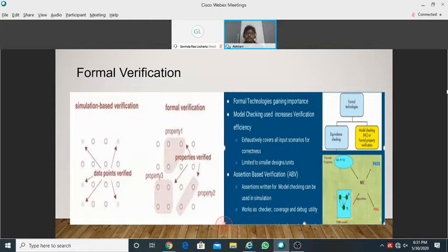Okay, so that is why we need to know what we need to use formal verification for. If you see, formal technologies have two points here. One is equivalence checking. It can be used for equivalence, like given any two inputs, it could be a netlist or a design, are they equivalent? That is one particular application. The other application is model checking, where you create a model based on the properties on the design, and you try to get your sample space or the data space verified.